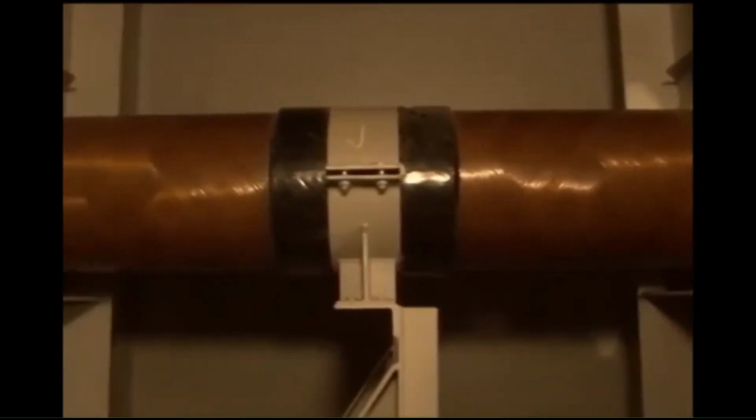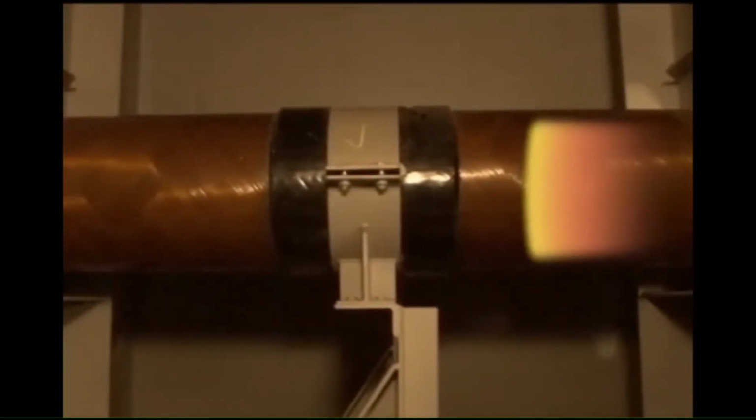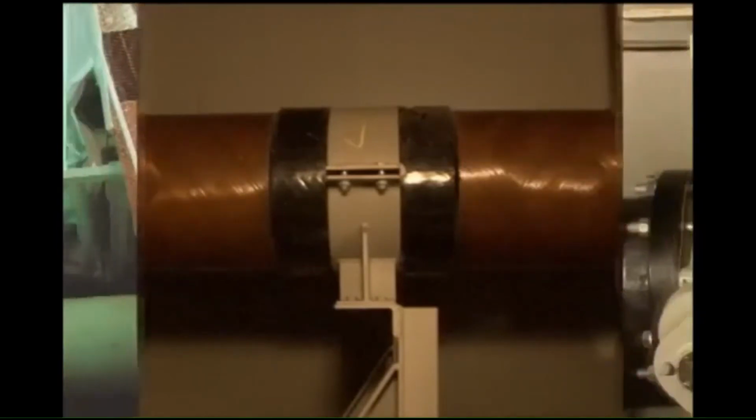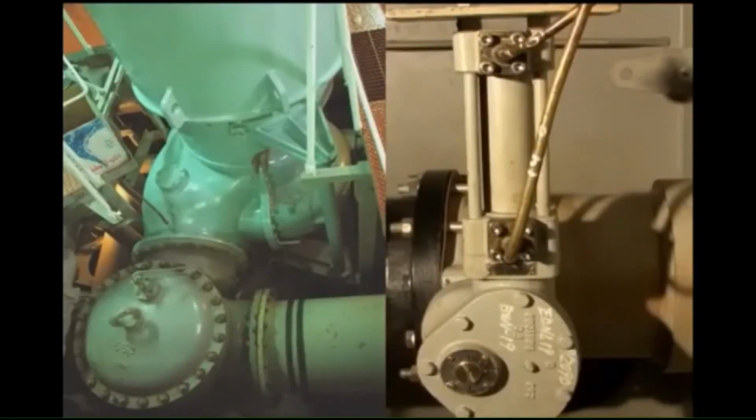If flow velocity within the pipeline suddenly changes due to valve operation at the start of or during pump operation, the pipeline internal pressure increases momentarily but sharply. This phenomenon is called water hammering. Water hammer can damage the pump casing, valves, and pipeline.